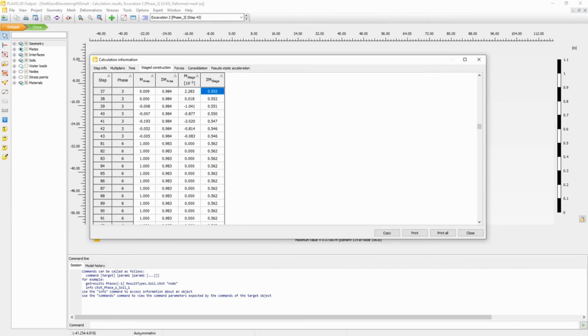This moving backward is in fact controlled by Plaxis through what we call the arc length control. The arc length control basically starts to control the amount of incremental change of out of balance, such that the resulting incremental displacement does not become too large.